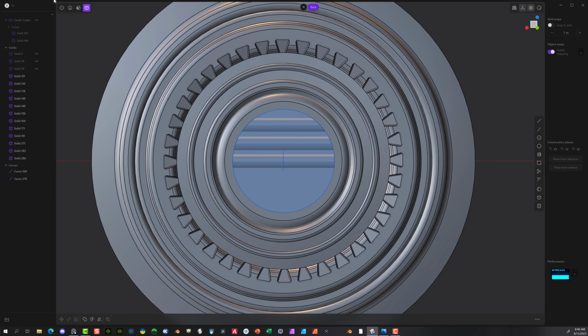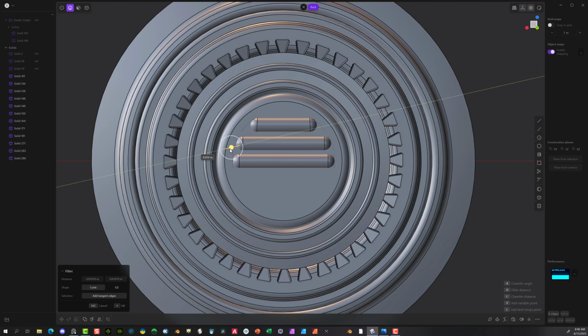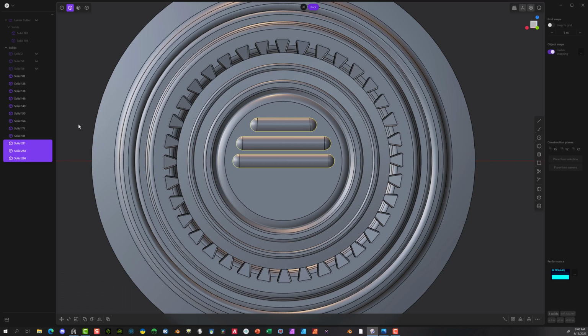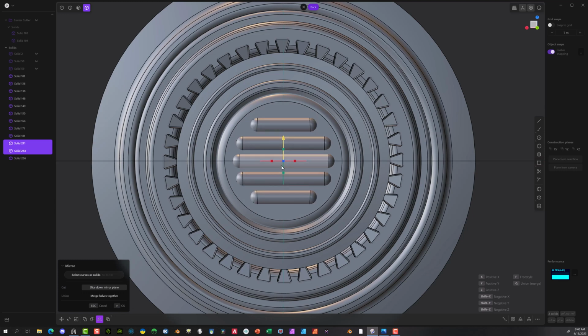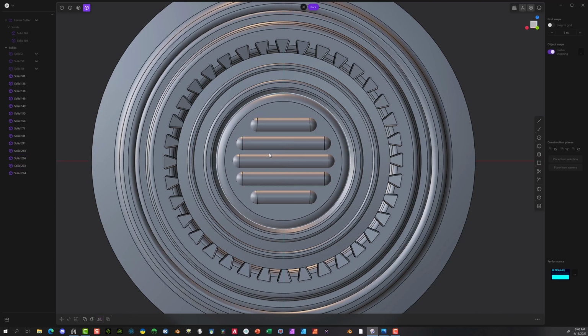And what we could do now is go ahead and get rid of these curves. Those two curves. Okay, so let's go ahead and select this. Hit the Shift key. Select all 6 of these. And we're going to pull this out so they're rounded like that. Okay? Say okay. Now what I'm going to do is select the object tool again. This and this. Both of those two, hit the Shift key. We're going to hit the mirror key. And we're going to select the green section so that does the opposite. There we go.